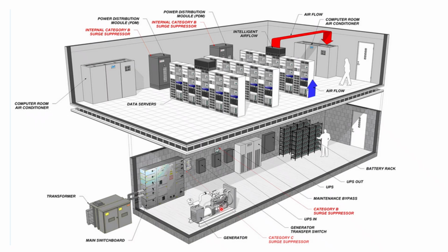That means when the transformer fails, the load is given to generators. Then you can have UPS also. The generators are generally designed for half the total load. The remaining is not supplied.